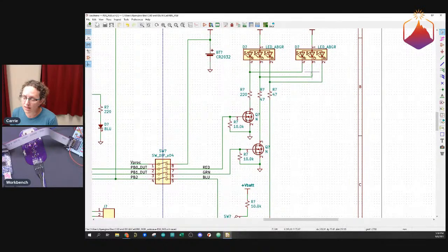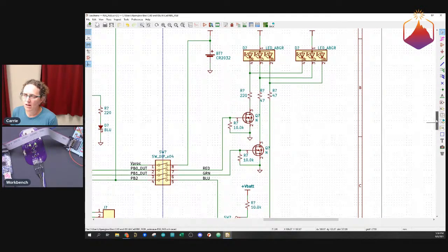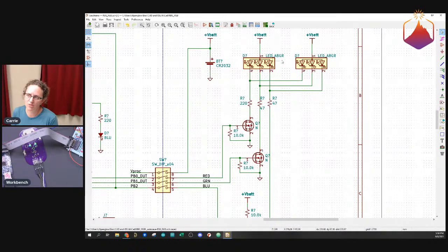We have tied the LEDs together, the red, the green, and the blue LEDs together. It's probably a little bit more correct for them to each have their own resistor and to be tied together after the resistor. That accounts for differences within the manufacturing batch of LEDs. If this red LED is just a little different from this red LED, then they might generate different voltages. They might have a different voltage drop, and they might start to fight with each other a little bit. Honestly, for this, it's probably not going to be a big deal. LEDs are pretty consistent these days. I'm not worried about it.